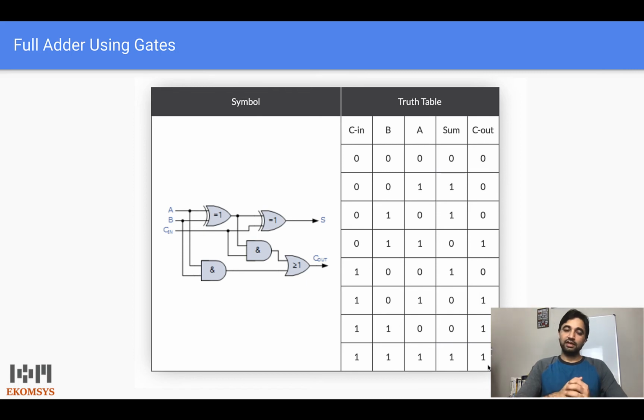So the reason I gave this example is so that you can visualize how numbers are added within an electronic circuit. What happens underneath a chip is that you have this combination of gates, and the instructions that you give to the CPU or to a microcontroller or any chip, you are kind of toggling the inputs, whether it's 0 or 1, and depending upon the instruction that you execute, you get the output.